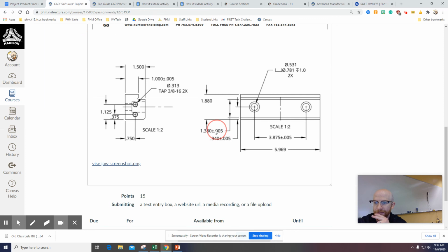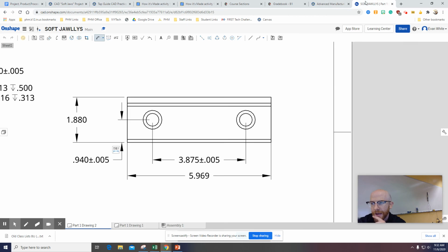Now, the next dimension I'm going to do is different than the one you're seeing here. It looks almost the same, but it's a little different. Basically I'm dimensioning from the bottom to the next horizontal line, not the one above. There's 3 basically. There's the top, and then there's the top of this semicircle we created, and the bottom of the ledge. So we are doing it to that bottom ledge part.